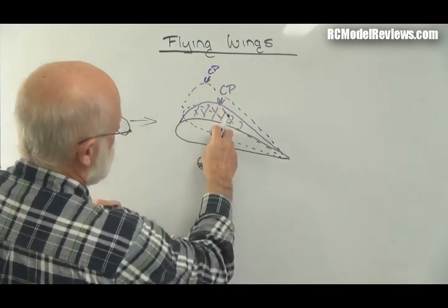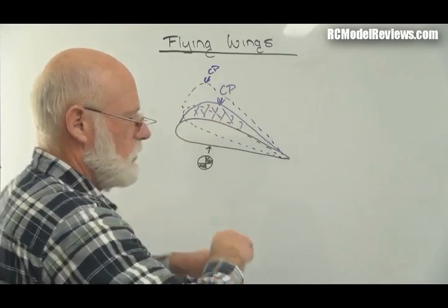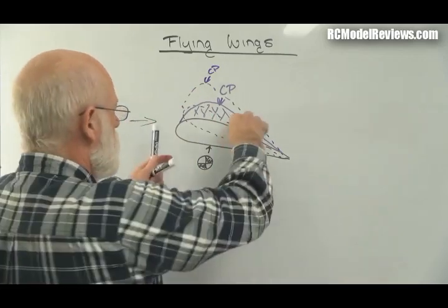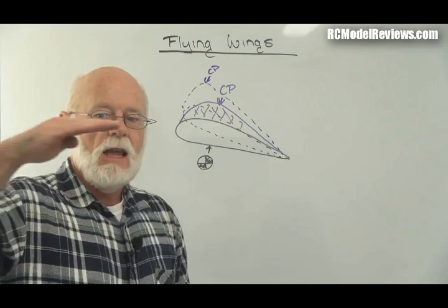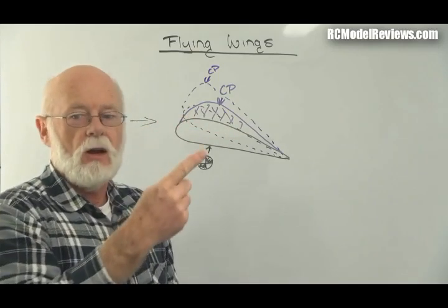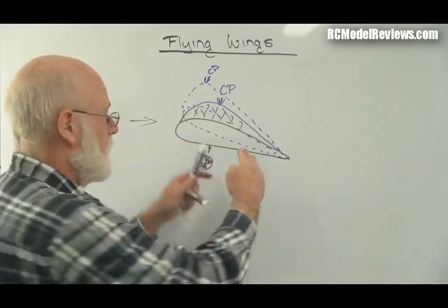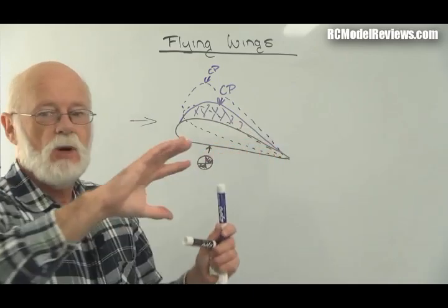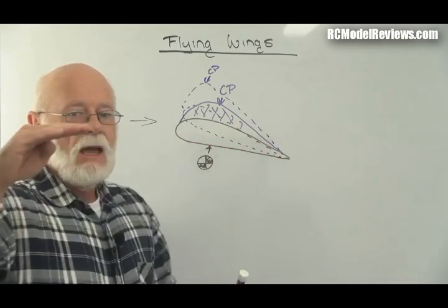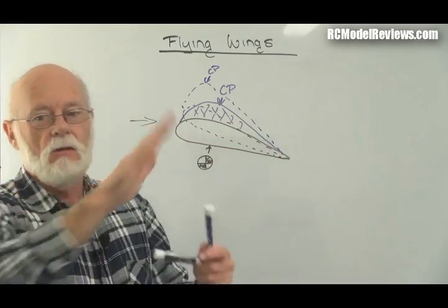So if you look there, we've got our centre of gravity here, our centre of pressure there. So the centre of pressure means that it will try and rotate the wing around the centre of gravity. As soon as the aircraft pitches up slightly, it will try and flip right over. Conversely, if the aerofoil noses down, then the centre of pressure would move towards the back of the wing, and so it would tuck under. It would nose up or tuck under.